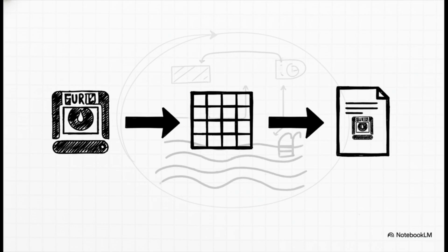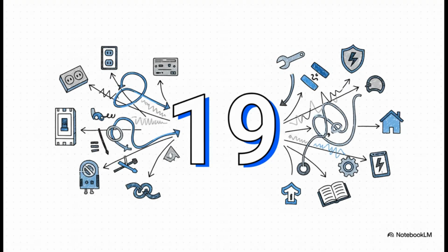And even more critically, fire alarm systems, Article 760, have their own strict rules because their reliability has to be guaranteed. You can't have a fault on a regular lighting circuit take out your fire alarm. You absolutely cannot. That life safety system must survive. Which makes this shift to high voltage even more profound.